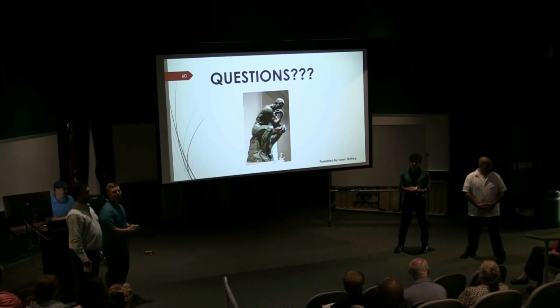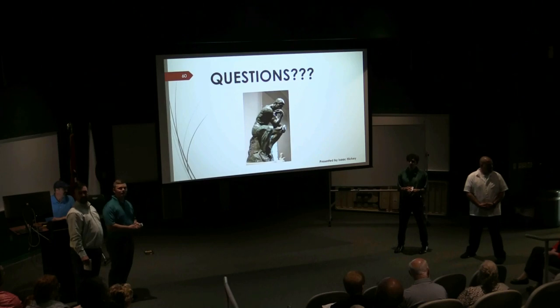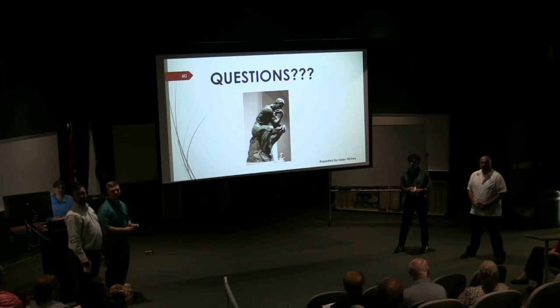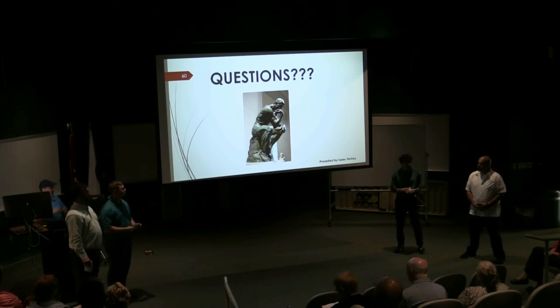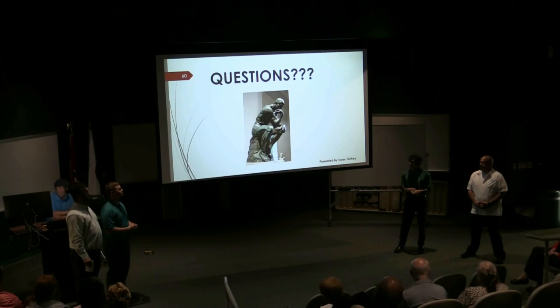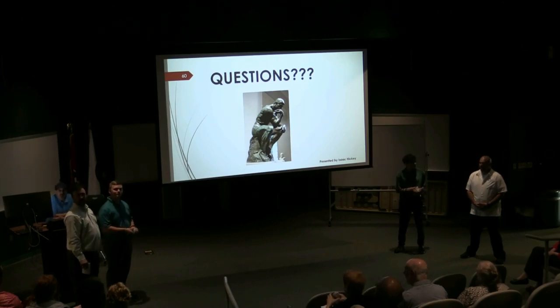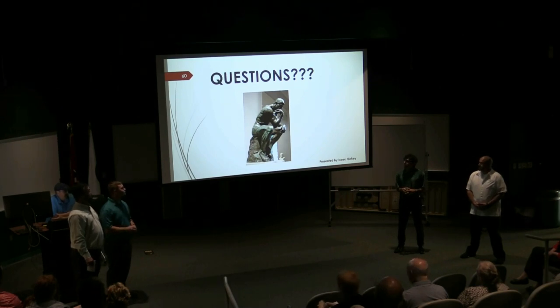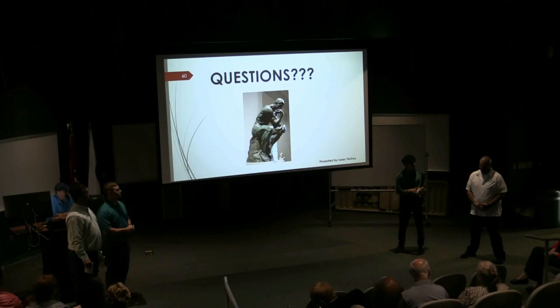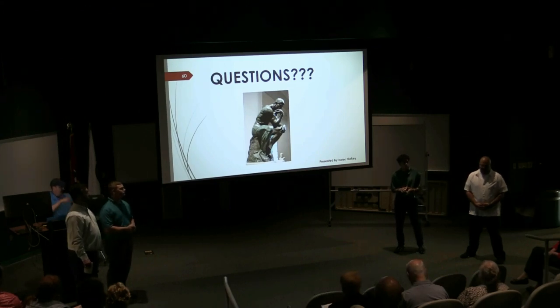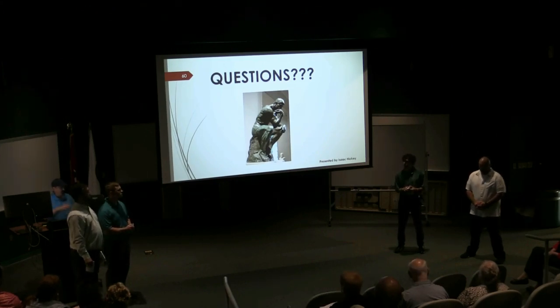You have more reactions in the reactor, mixing, right? Turbulent mixing. You get the same residence time too for all of the fluids. Okay, good. Also good for heat transfer too, right? You want mixing, right? You must have that stuff moving around in there. If you're laminar and you're trying